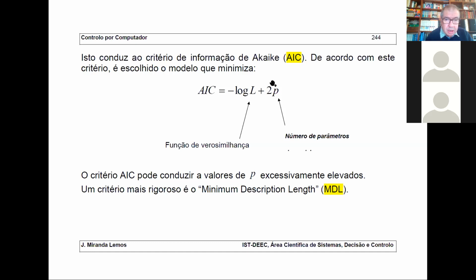Okay, so this gives you the capacity of your model to be close to data. Okay, so here your model is close to data because you are putting a lot of degrees of freedom, and here it's because it's the intrinsic explanation effect of the model associated to the estimate of the parameters. Okay, and there is a trade-off between these two. So if you look at the function ARX or ARMAX, sorry, they do not estimate the AIC, but they estimate something which is equivalent.